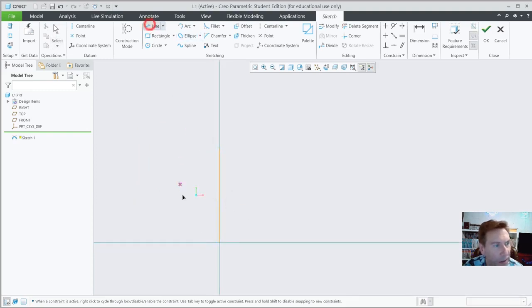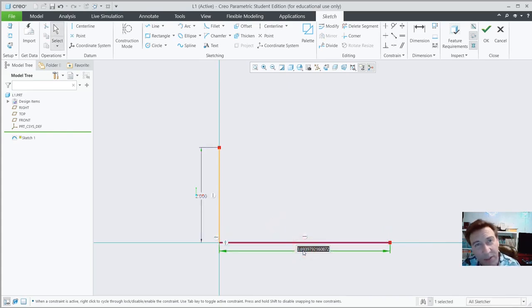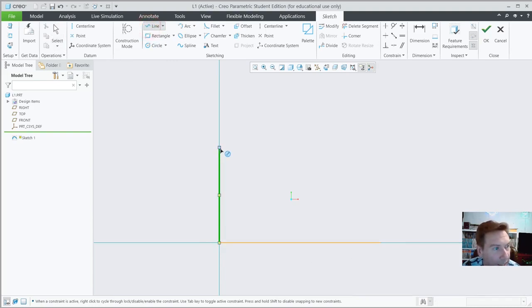All right, now I'm going to go over here to the line tool and continue on from down here. I'm going to drag this across, click, middle click, drag that down. I could do these all at once. I'm just showing you for new users so you get the proper scale. So that will be 3.5. Now you could go back to line, draw this across, and now you don't have to put in the dimensions as much. Just draw a short little line there, draw one down here.